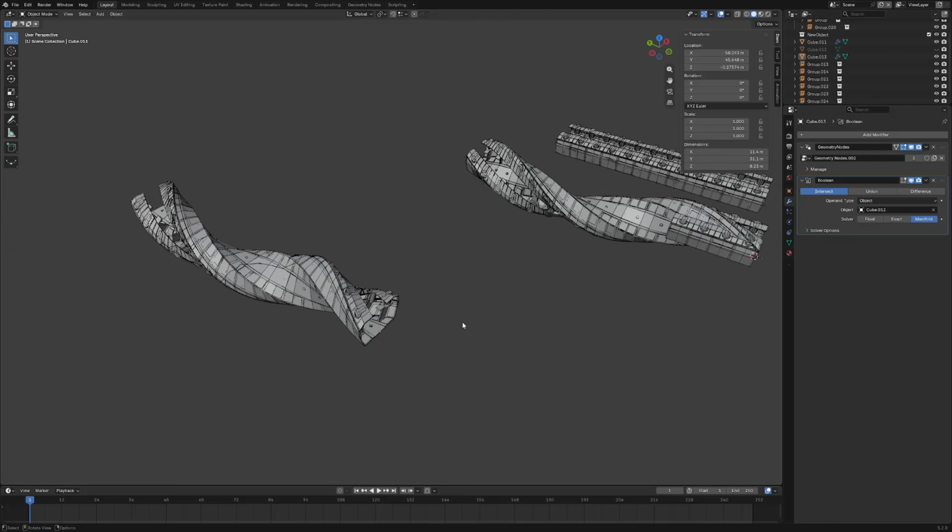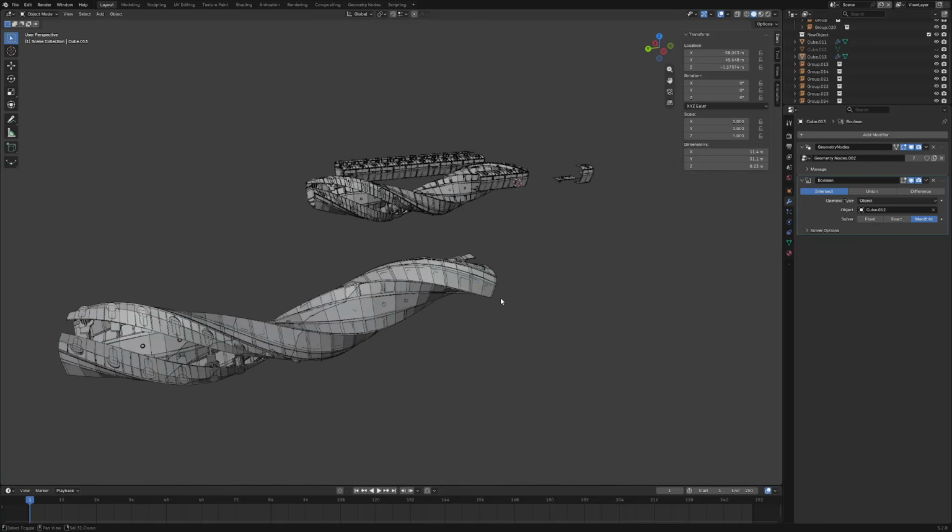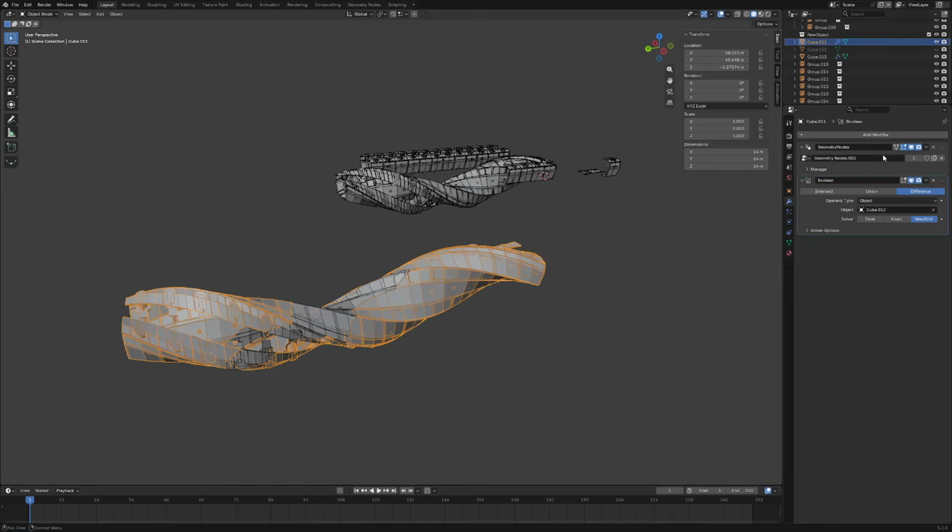The only thing is it's hard to do in Blender because first, there was never a grouping system, right? The way you group is still using collection instances. So it requires that second scene to store the objects. And then ultimately, you have to do the weird GeoNodes workaround to actually use modifiers. We can't really update the pivot points all that well without going into the group itself. So there's a little bit of back and forth with this.